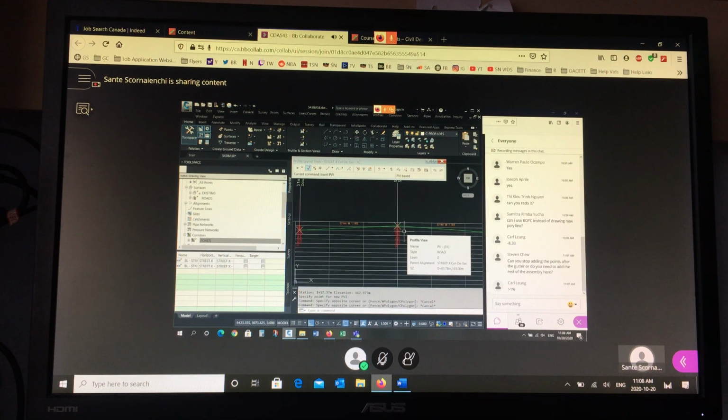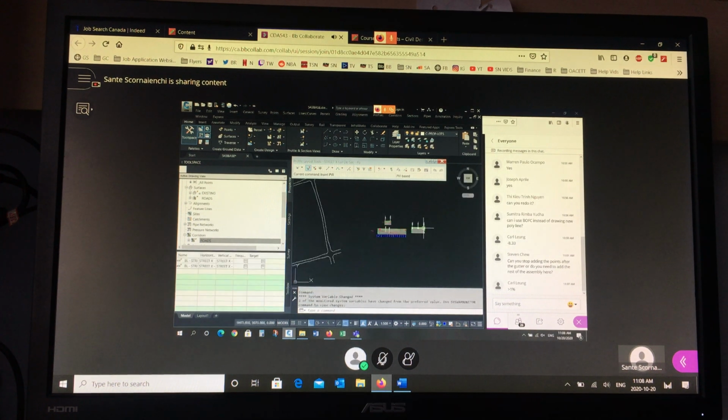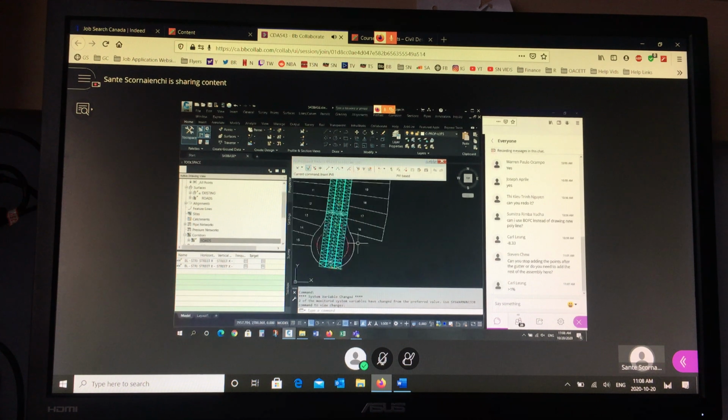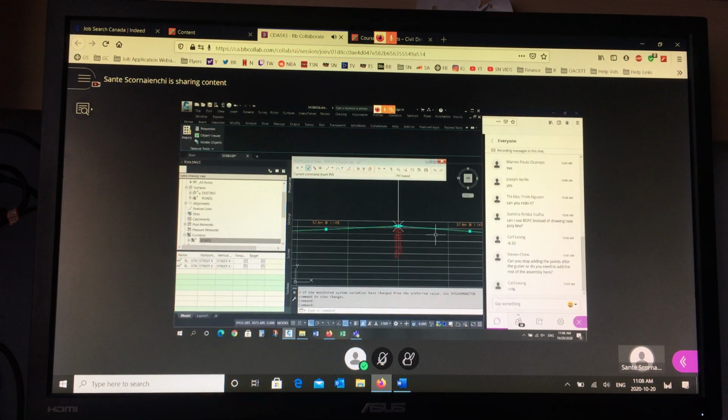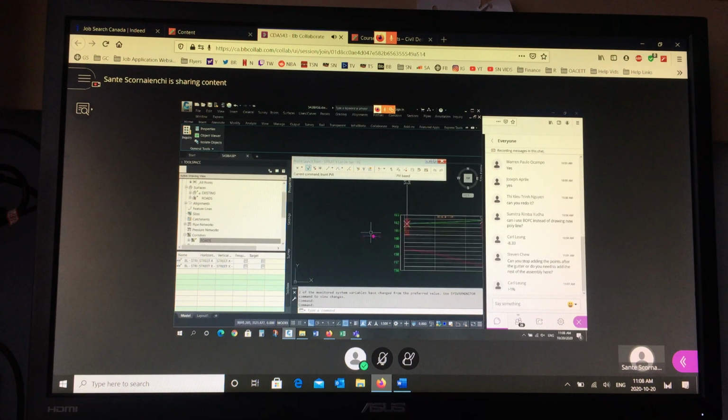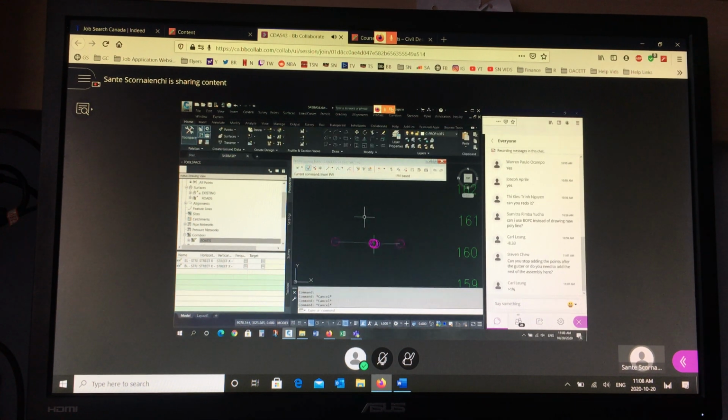Okay, so I'm not designing anything here. I'm just creating the explicit data required for the modeling. So now I have, just like any other corridor, a horizontal alignment, a vertical alignment, and a cross section. The same one. I want to drag this all the way around. So now I have plan, profile, cross section, the 3 basic building blocks of a corridor. I'm not going to create a separate corridor. I'm going to add to the current corridor, and I'll have one model that shows all this.